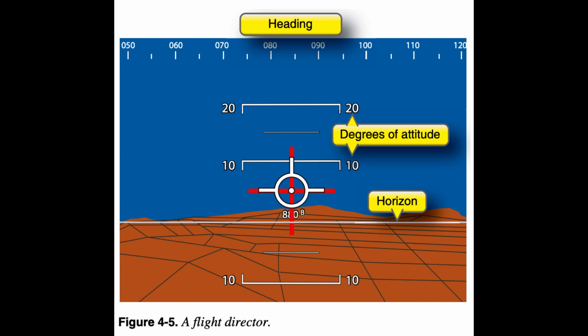Common error: blindly following flight director cues. The convenience of flight director cues can invite fixation or over-reliance on the part of the pilot. As with all automated systems, you must remain aware of the overall situation. Never assume that flight director cues are following a route or course that is free from error. Rather, be sure to include navigation instruments and sources in your scan. Remember, the equipment will usually perform exactly as programmed.